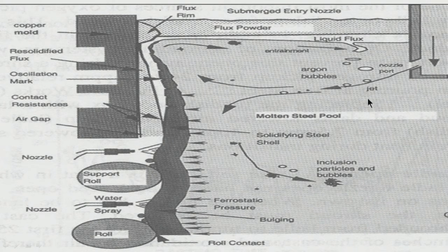So, the liquid steel is supported by the solid shell here. Thus, the solid shell must have adequate strength, otherwise there will be rupture of the solid shell and there will be a breakout, and there will be chaos. The whole casting has to be interrupted. The casting floor will be flooded with liquid steel. There might be an accident. We have to be very, very careful about that. So, the shell thickness is very important.